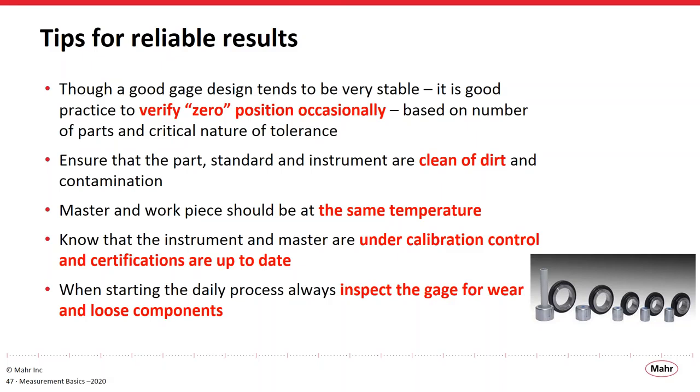Make sure that the master and the workpiece and the part are all as close to the same temperature as possible. As you know, different materials expand at different rates because of temperature. Try to keep those as close as possible. And also make sure that your masters and instruments are under calibration controls and certifications are up to date.